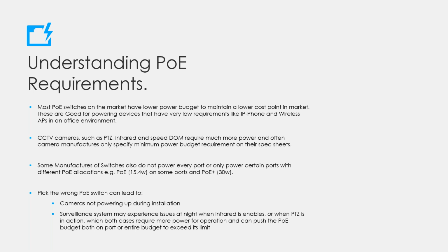features on the switch must be configurable, so you can support all of the standard devices and also the devices that do not support any PoE standards, so non-standard devices. So when you pick a wrong switch for the job, it might lead to the issue that it cannot apply to the standard or lack of standard that the PD requires, so you can't manually adjust it to the requirements of that powered device.